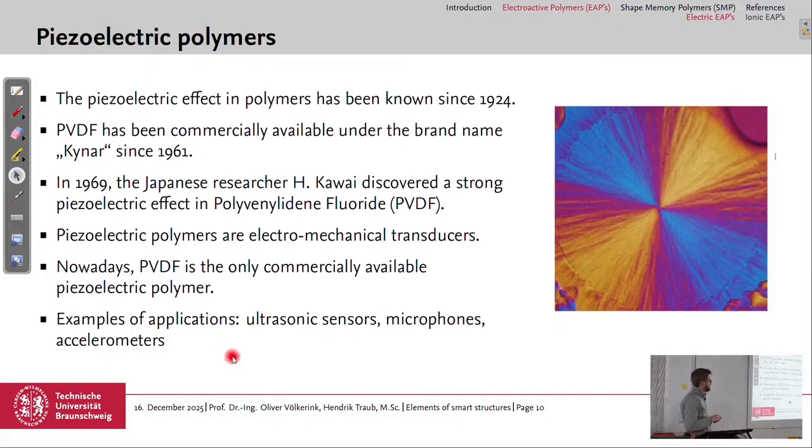And PVDF is also the material we used in this multifunctional bond line I had in the first lecture for the crack stopping. So PVDF gives some improvement to the mechanical performance in this adhesive bond line due to its crack stopping features, a toughening of the material. And the original idea was to use this piezoelectric effect to sense also the adhesive bond line.